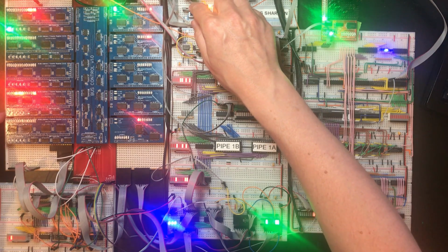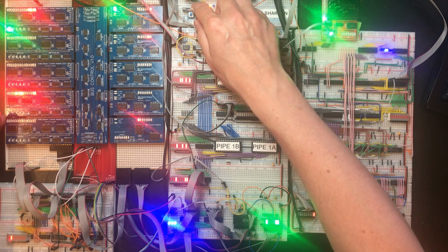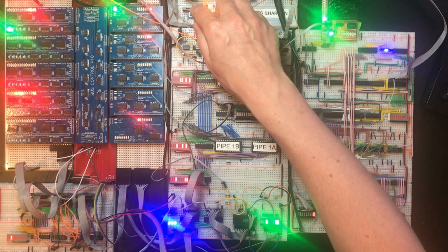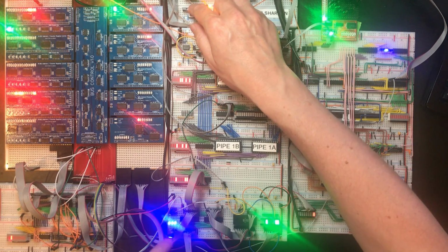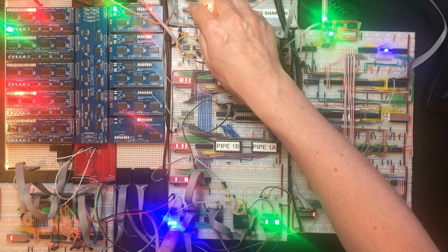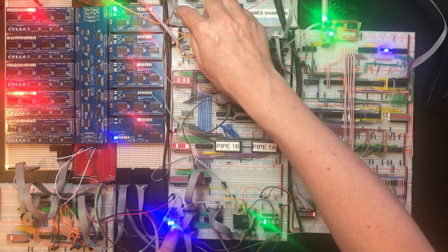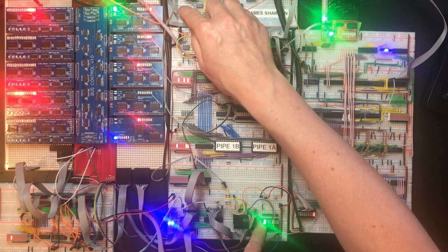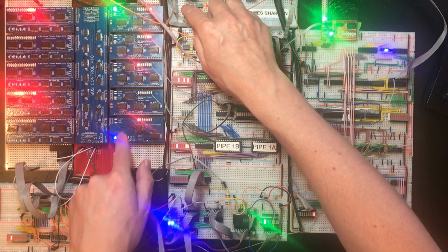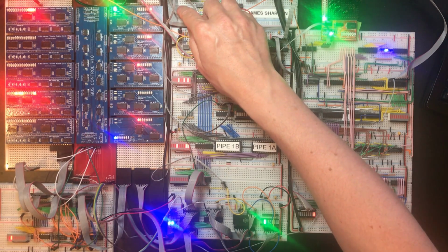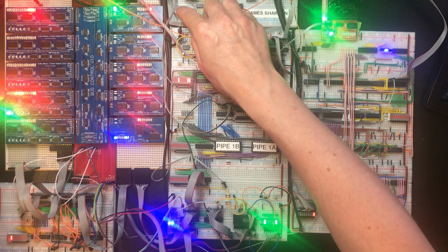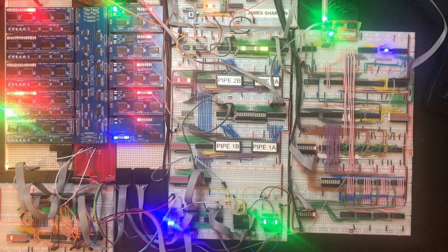Okay, so now you should be seeing the move C, TX. So we should be seeing the assert line drop low. So in that, 128 is on the bus and is into C. So then it was 130 in the next address, which is what's being pointed to by SI. There, it's worked. Excellent. The next instruction about to get loaded in is the move TX, A.